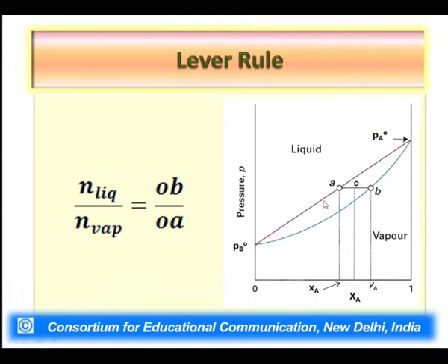So, all the points on the purple line represent the overall state and the liquid phase composition, and therefore this point A on the liquidus curve is the point on this horizontal line which connects with the liquidus curve. Point B, contrary to point A, connects to the vaporus curve and therefore represents the vapor phase.